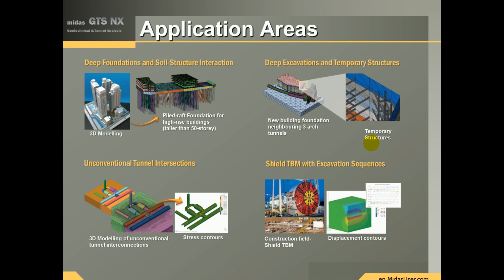So just to go through some of the application areas and key things to focus on within industry. We can do the piled raft modelling and nonlinear pile soil interactions, key for in-city areas, so we can see the reactions on other buildings and tunnels and things like that. We can do the excavation supported with temporary or permanent structures, so another key one for excavations and construction stages.